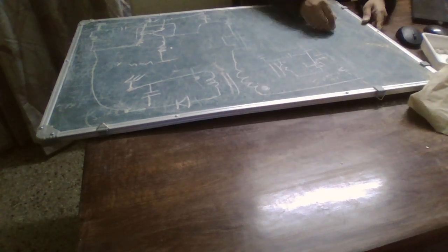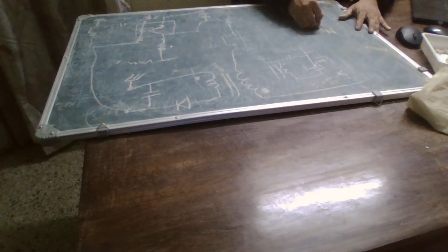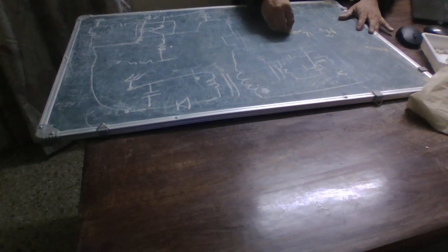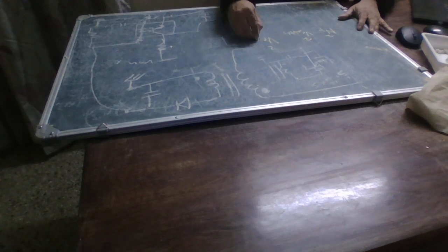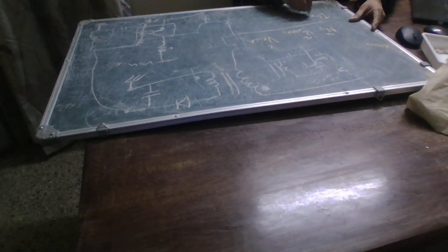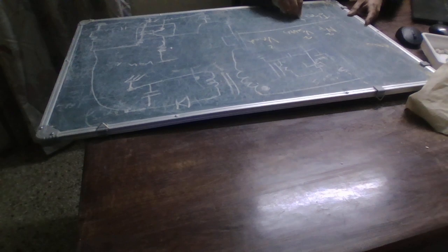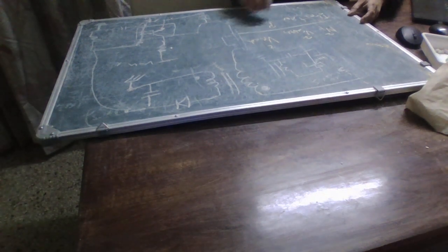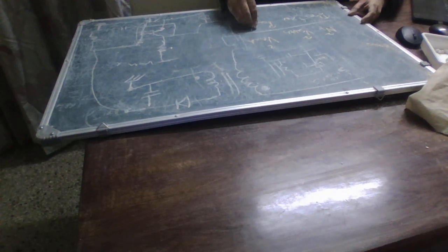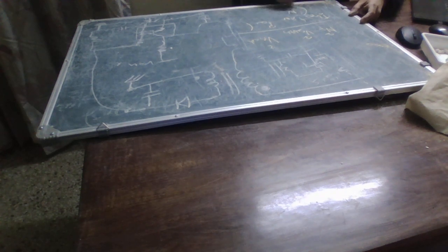The formula that we are going to use is the number of primary turns square, the supply voltage square, V load square, by ILRR, the primary winding ripple current ratio, into switching frequency, into P out, into the number of secondary turns, into V supply plus NP into V load, the whole square.